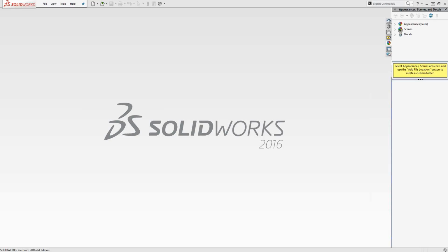This video's topic is custom turning tools, or specifically custom turning holders of turning tools. This video is actually a companion video to the STL holder creation video, in that I'm going to use an STL file to define my custom shank for my standard insert. So this doesn't cover custom inserts. This just covers the custom shank you may use. You may have custom shanks for additional clearances or anything like that.